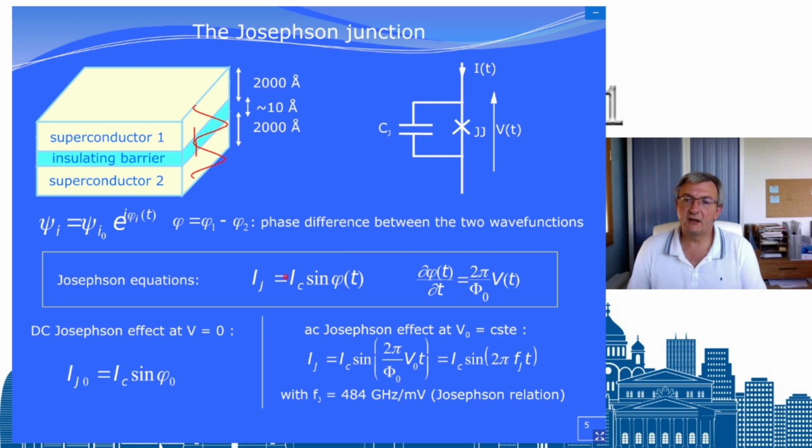I will not mention as well for the moment on this equation the quasi-particle current, because of course the Josephson current corresponds to a zero resistance, right? You can have a current without voltage in DC, at least with continuous signals, and then it means it's a shunt in some way. So the current will not go through a resistive path if it can cross without resistance.